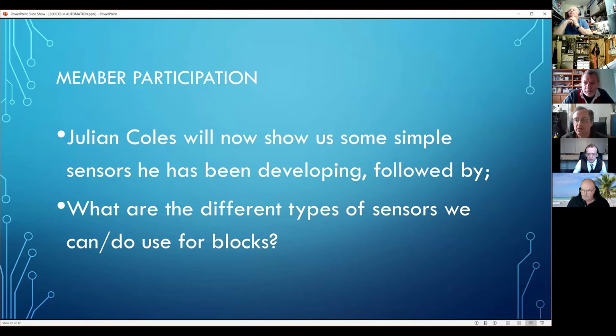It occurs to me that if one has two contact sensors along a length of straight track, then a train passing over those can calculate both the speed and the length of the train, as long as there is debouncing on the contact sensors, so that a gap between a loco and a carriage or a loco and a wagon wouldn't be registered as the end of a train and the beginning of another. It would calculate from the beginning of the locomotive to the passing of the last vehicle, and could therefore use software to say, okay, this train travelling at this speed must be this length.